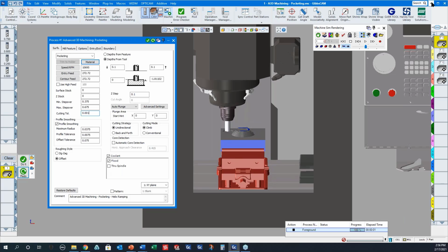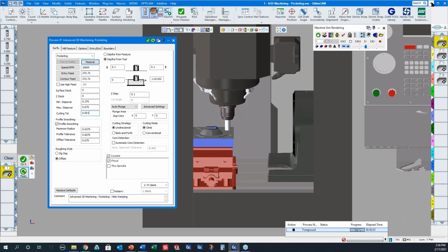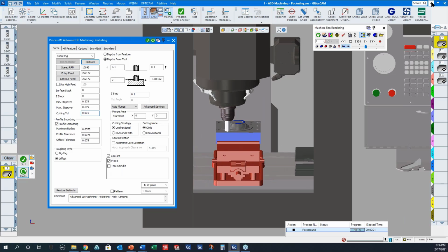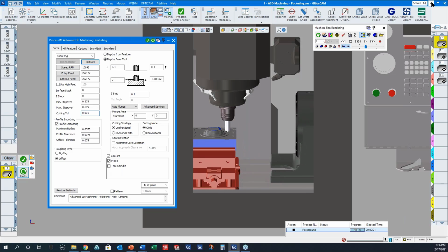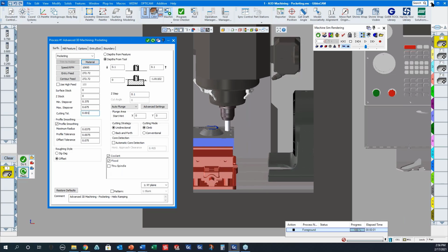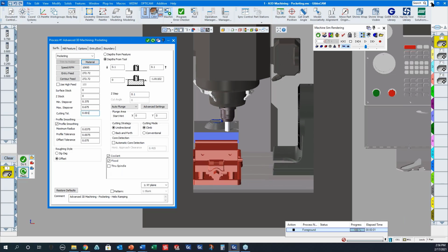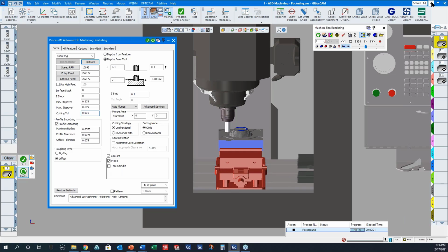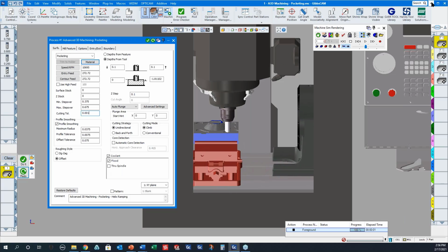We had our Haas post modified so that we get a G187 P1 for all traditional roughing toolpaths, but we use a P2 for things like helical milling. And for all 3D toolpaths and all 5-axis simultaneous toolpaths, we use a G187 P3, which is the smoothest. It may take a few minutes longer to run a program in P3, but you get a better looking part.